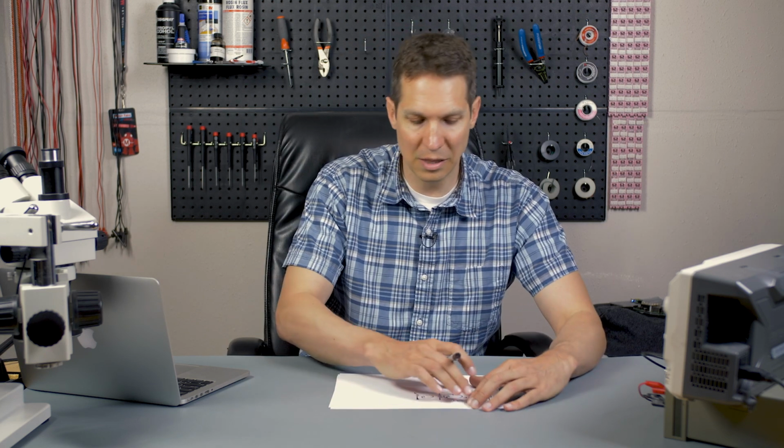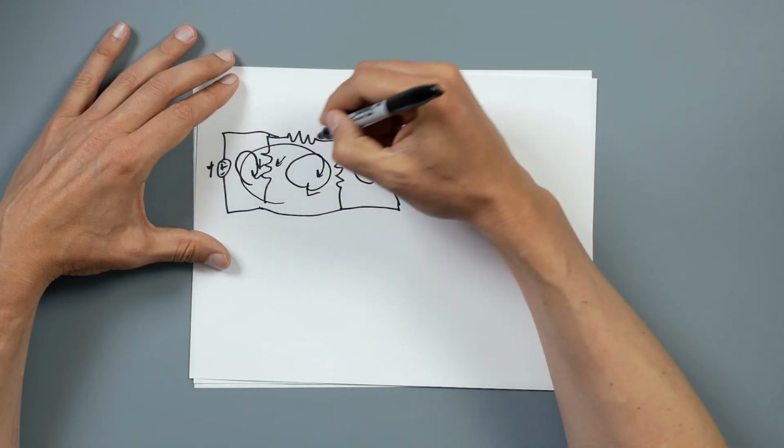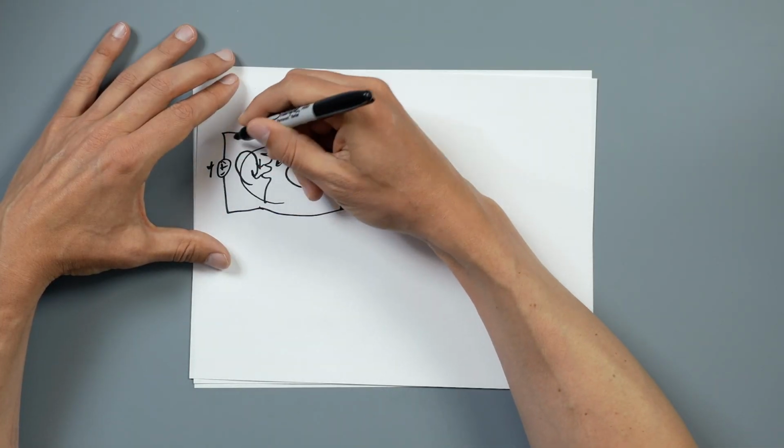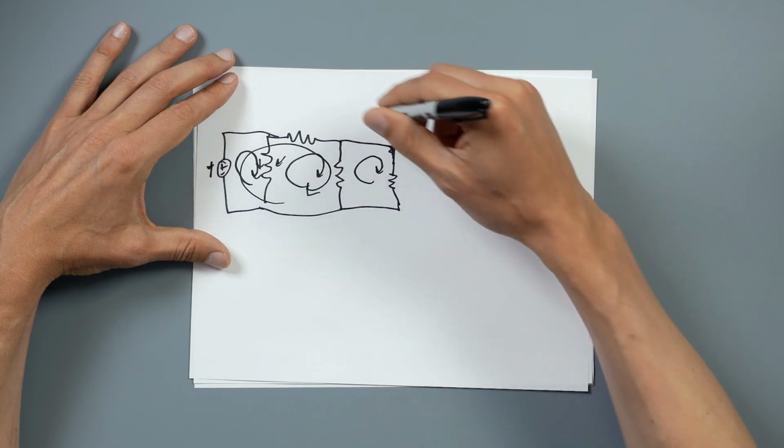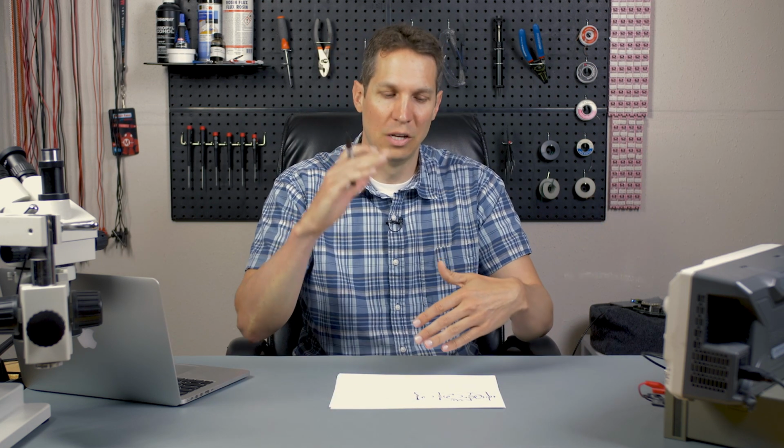So this is, again, the basic idea: as you're going through mesh analysis, you will say, okay, I know the voltage across that's going up, the voltage across that's going down, and that's going to equal zero, and then you just set that up mathematically and come up with a solution. And that's really it. So I created another couple of steps. I made one modification from the KCL steps that I had, and I included one final step explicitly in there. But in general, it's fairly similar to what we did with KCL.